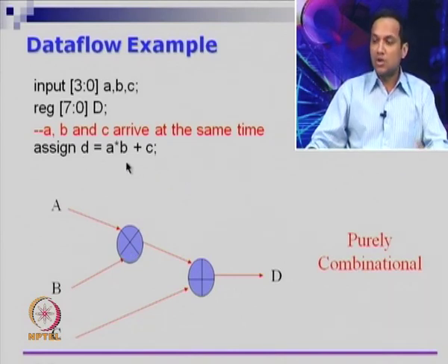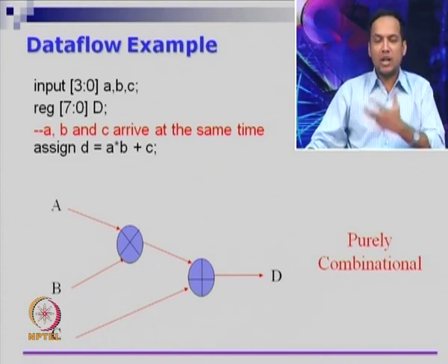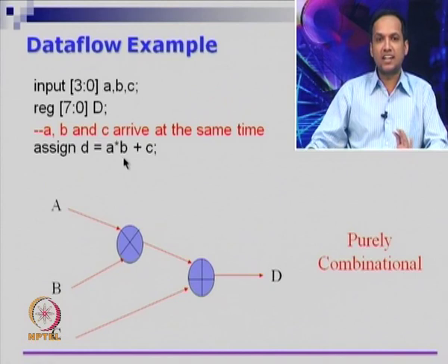So you could also go and write this whole thing in a structural manner. So by that, for the adder you may actually use a ripple carry adder, for a multiplier you may come up with your own way of doing multiplication of two numbers and so on. But if you do that, the programmer's intent is buried inside lots of lines of code, whereas this is very clean and many tools can immediately understand that you are looking for multiplication and addition.